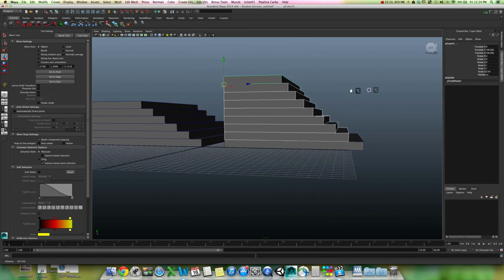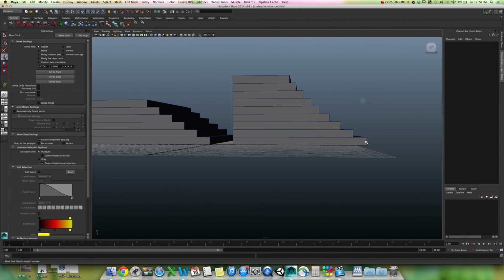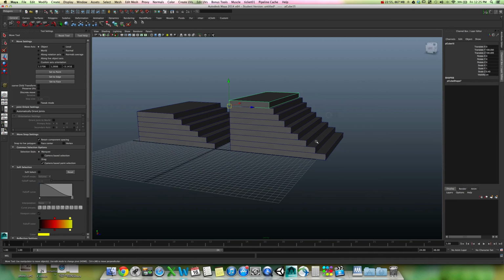Now you see I created a staircase a lot faster, but what I was saying was that every time it scales this, right, this one will be 0.9, but it will scale 0.9 by 0.9. You see, so it takes 0.09 out of it. And you can see it's exponentially decreasing in the amount that it scales it. Why? Because you didn't freeze the transform every time. Because it's taking 90% of 90%, which is 0.81. So it's not exactly the same, but it's a way to automatically iterate creating a staircase.